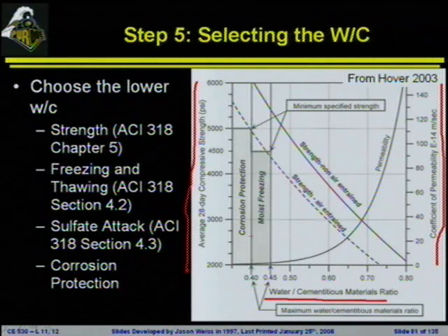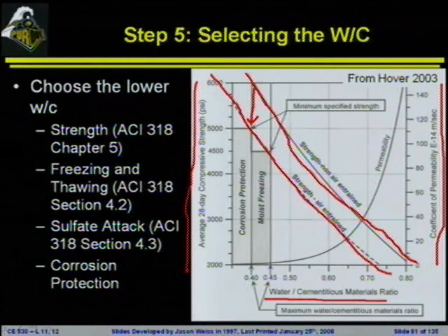And what you will notice is, much like we saw in the graphs that we were drawing, we've got the line for the non-air entrained concrete. Water to cement ratio goes down, the strength goes up. We see that that line shifts for the air entrained concrete because we have porosity in the system. So again, that line makes reasonable sense to us. And then what we can see is there is another line that starts to come onto this graph, and this is the permeability. This is our coefficient of permeability.